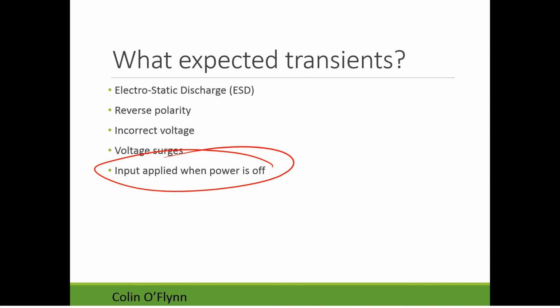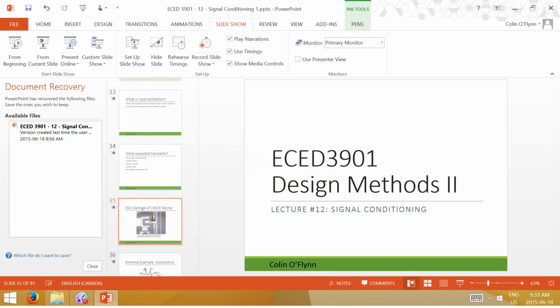Or if you get a type of meter where you can switch the mode dial, some of them will blow up if you have it in the wrong mode and you're measuring a high voltage. So I can show you that. I'll show you that afterwards because I don't have the link right there.